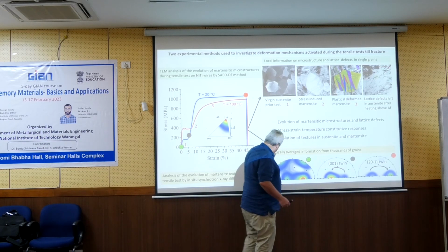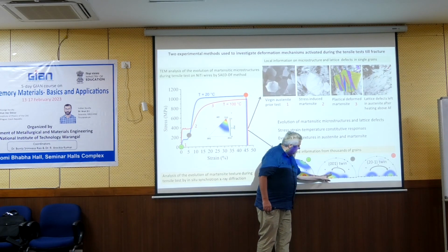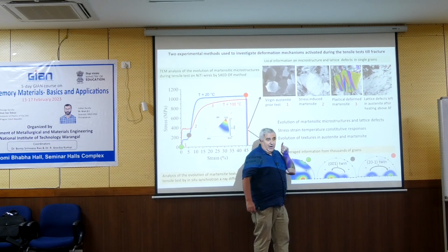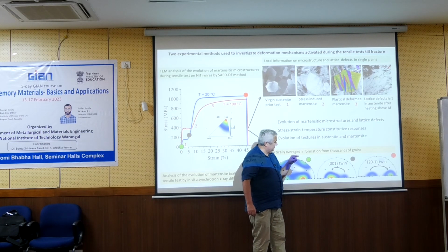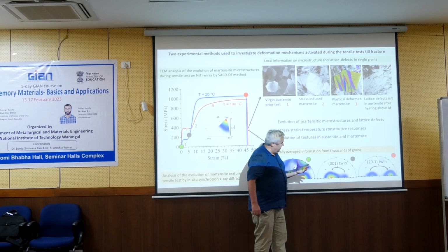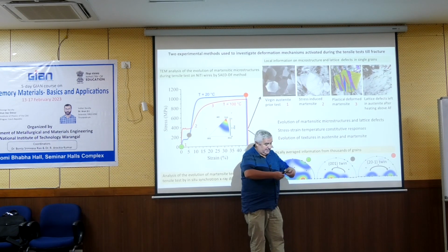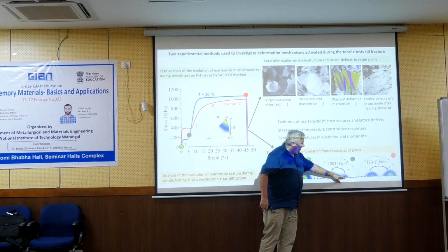This one will remain a little bit. This will remain, but 90% of the orientations will be here, which is one particular -103 direction or -102 when I take the directions in monoclinic lattice, which is the experimental evidence that in reoriented martensite, practically all martensite lattice is equally oriented with some remaining here.